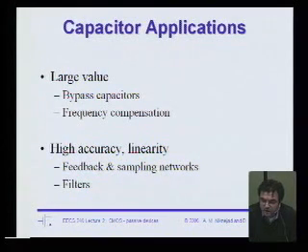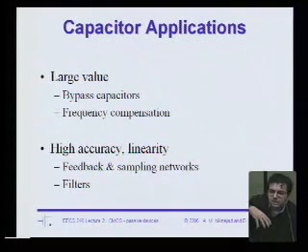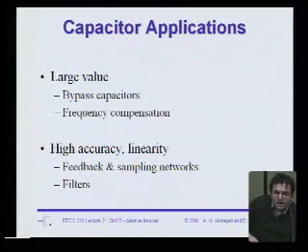Okay? In fact, this not only applies to integrated circuits, it also applies to power, like the power we get, the lights coming in. Anybody ever seen a bypass capacitor for power applications? They're big, right? They're physically bigger than we are. But if you drive by and you see like a cage with all these cylinders and wires coming in and out, that's like a bypass cap array.